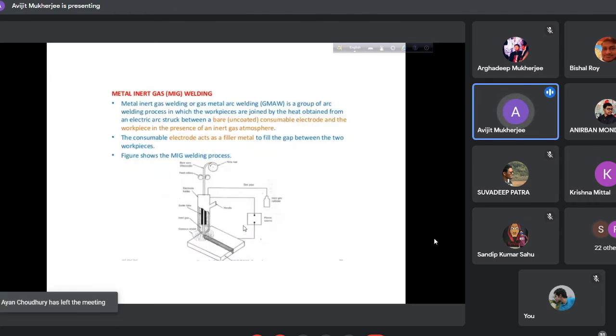And another TIG, tungsten inert gas. Another concept is MIG, metal inert gas. MIG, not TIG, MIG, metal inert gas, any metal other than tungsten. And here, this is a consumable metal, consumable. Now, what is the difference from an ordinary electrode? Here it is covered in, or it is working in a gas shield envelope. So that's why inert gas, metal inert gas, but in an ordinary electrode there is no inert gas. That is working under atmospheric air.